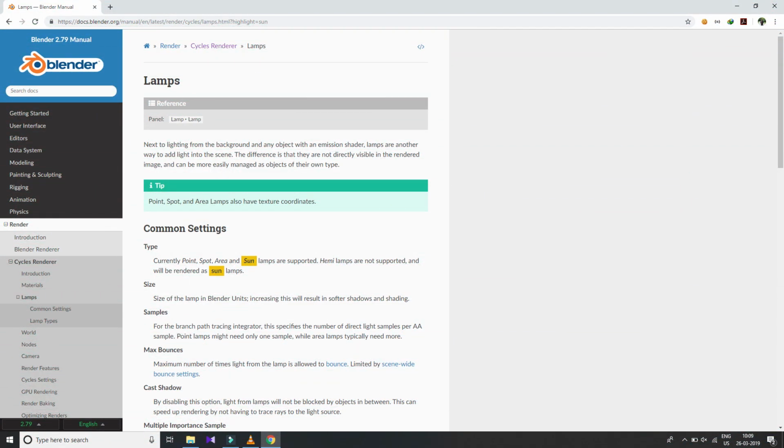It is very easy to add lighting in Blender. There are many types of lighting such as point, sun, area, etc. In this project we use sun. In Blender, sun is a light with parallel rays that will illuminate the scene with a bright even light. Because the sun is infinitely far away, the position of this lamp does not matter, only its direction.